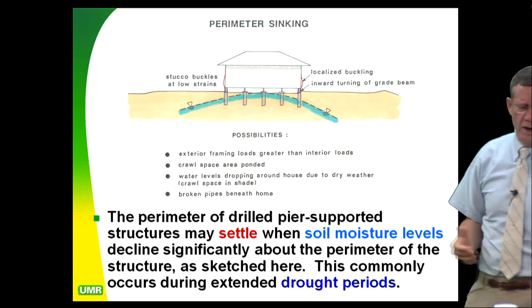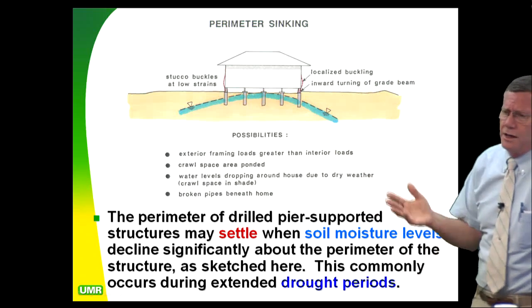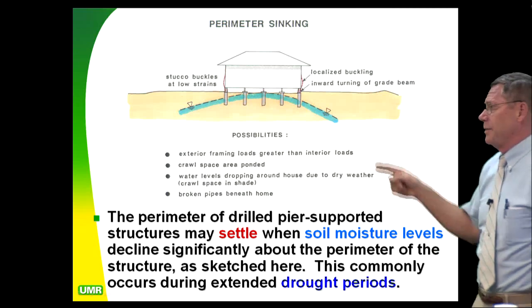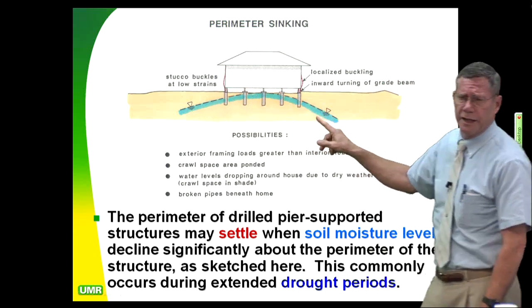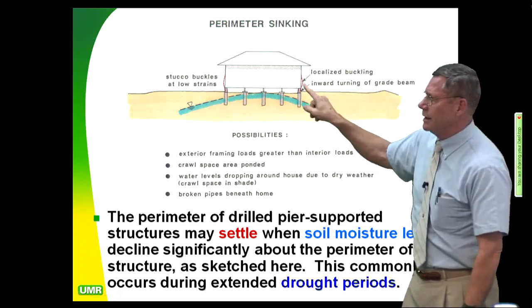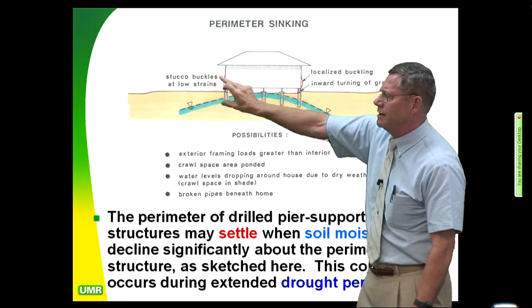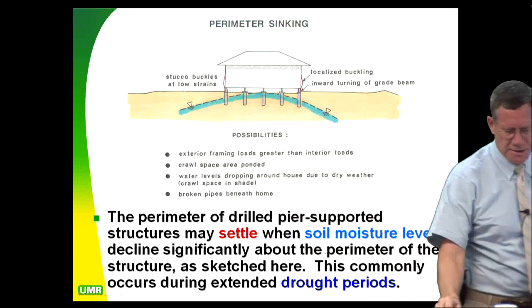So Honolulu Board of Water Supply told everybody, yeah, we're in a water drought situation here. Quit watering your lawns. So people quit watering their lawns, and what happened is they started seeing these kinds of situations. So they get an interior doming, and you'll actually see buckling right here, and buckling of the sheathing right there, because this is dropping on the edges.